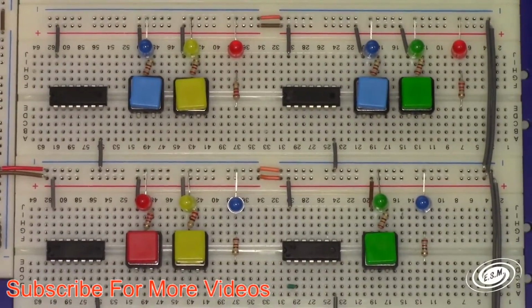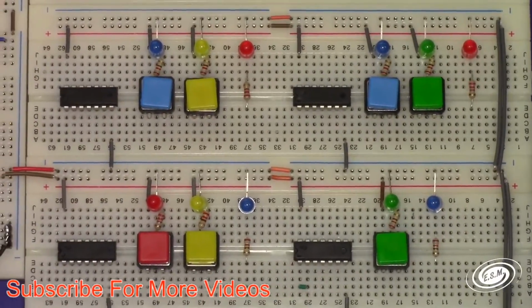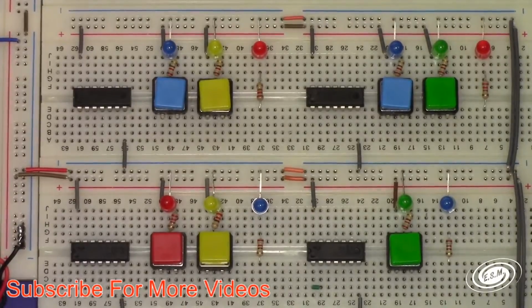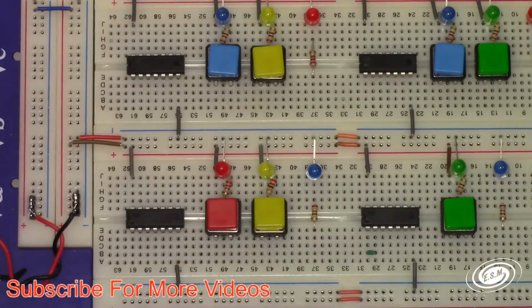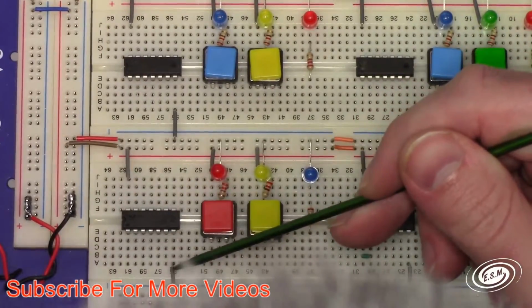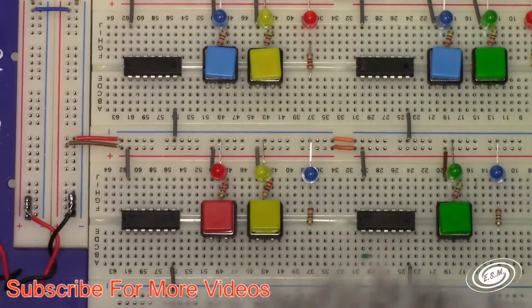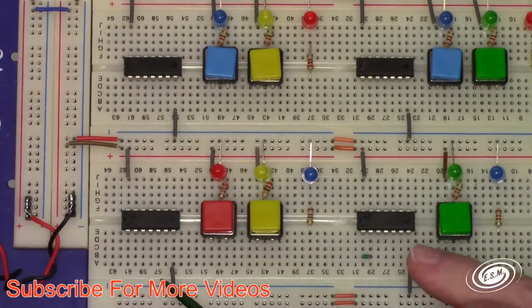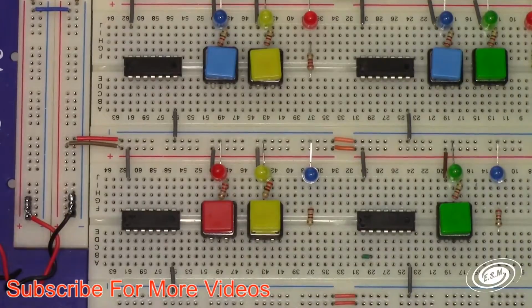Alright. So right down here we're going to hook up our standard NOR gate. If you take a look here, I have power on pin 14, and ground on pin 7. My inputs are 2 and 3, and my output is on pin 1.